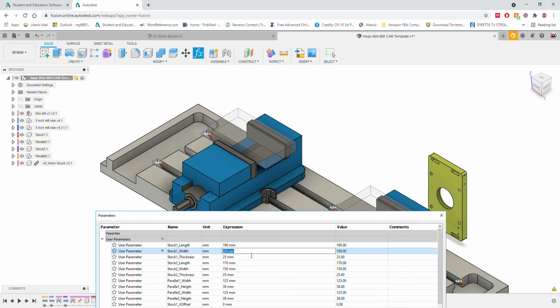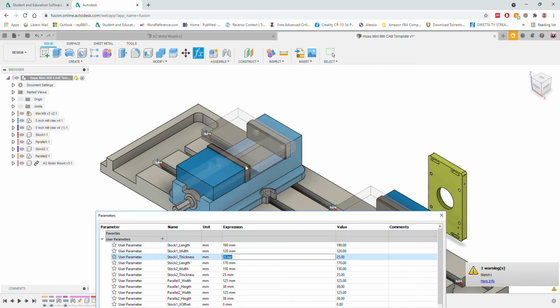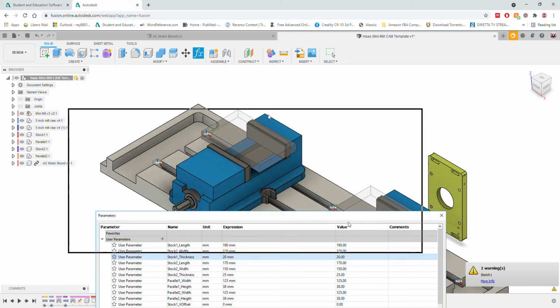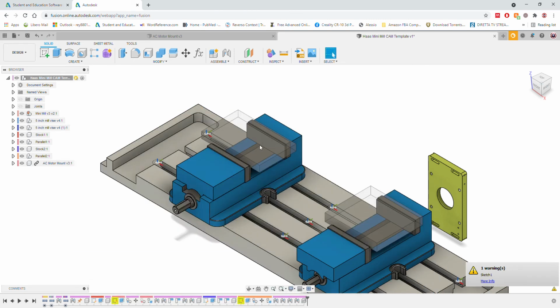The width, it's 111 if you have it precisely, or it can be more, let's say 120, and everything will adapt to that. And the thickness, you want 2 millimeter more. Say that you want to do the profile of the outer part, so you know that it's 15, plus 2 millimeter there is 17. 17 is difficult to find. Usually the closest you get is 20. Alright, that's done. Okay, and now you have the stock ready.